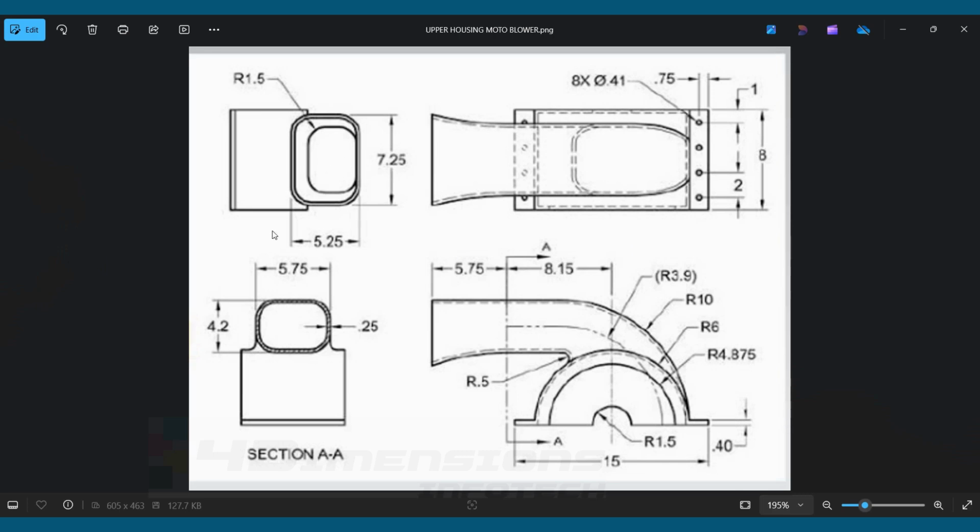The purpose of making this model is to understand how to make this part as well as to revise all the commands we have taken in Solid Edge in previous lectures. So here we are going to use loft command, sweep command, extrude cut, holes, etc. To start with, I'm going to make this lower case. You can see this C type case with these flanges on the sides.